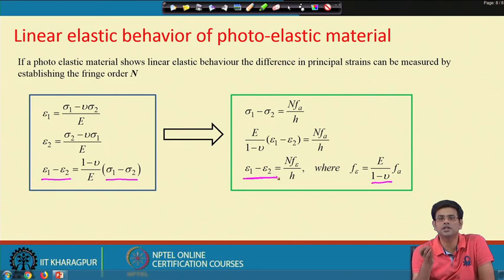We have derived the linear phase shift and the angular phase shift, and with these we finally write the stress optics law with the help of the material fringe value. The material fringe value essentially represents how light will propagate through a photoelastic material. That means the material has to have birefringent capability for photoelastic experiments.